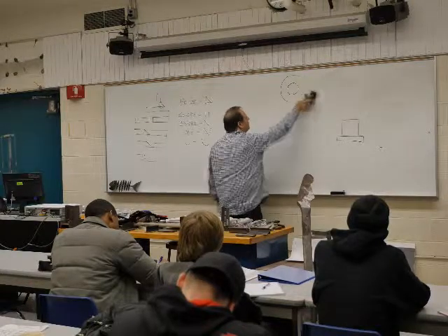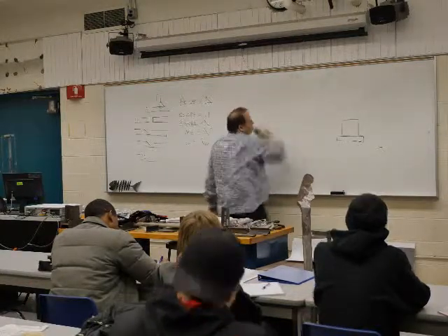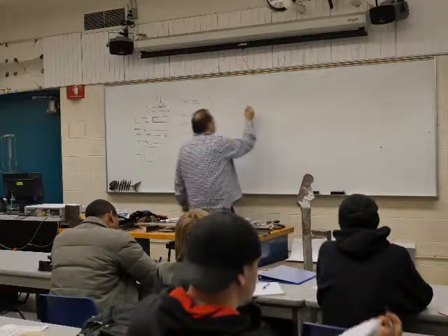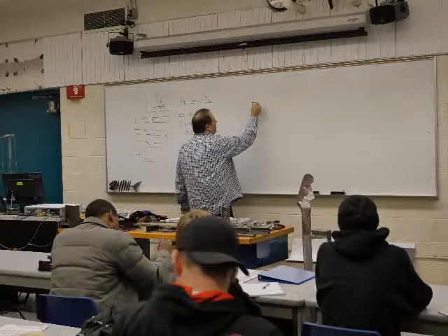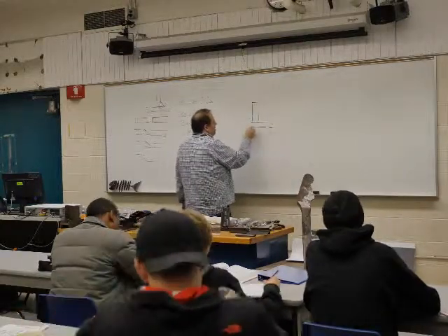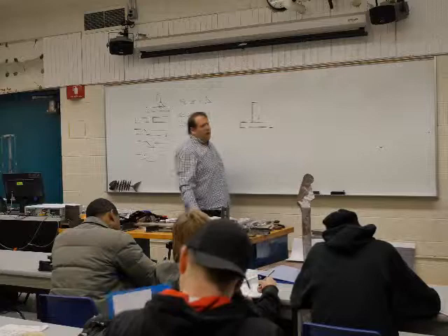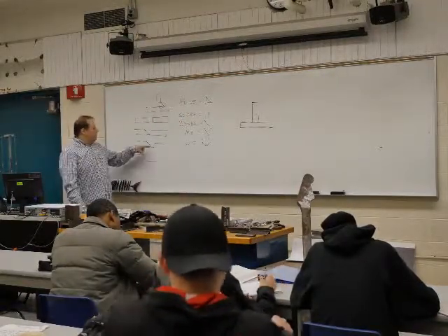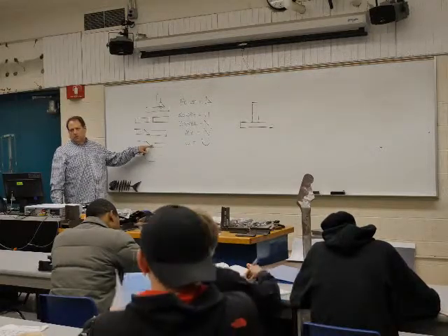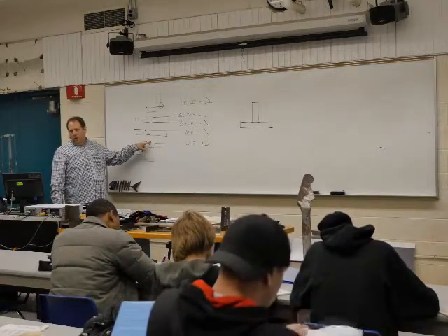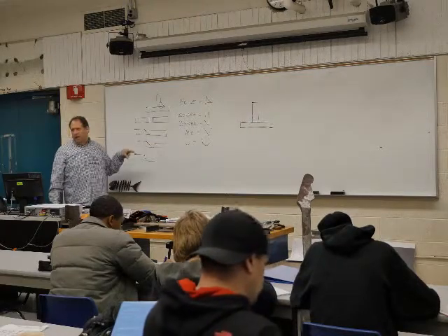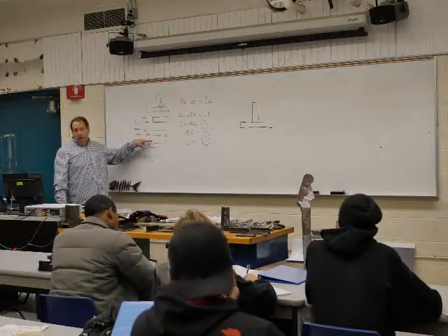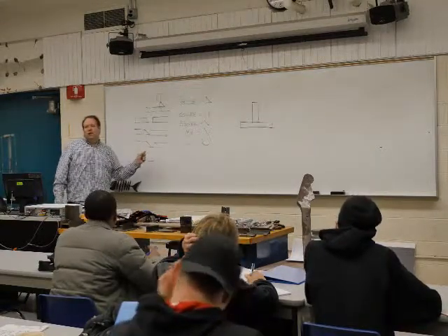Now, size of welds come before the actual weld symbol. And we're strictly talking about fillets again, because on a groove weld, we really don't have size of weld. If it's prepped like this, we have to fill that thing in anyway. So it's really not an issue about size of weld. You can have an issue of how much underneath or how much over the top, but as far as the size of the weld, no.